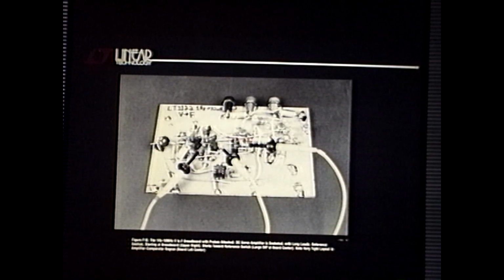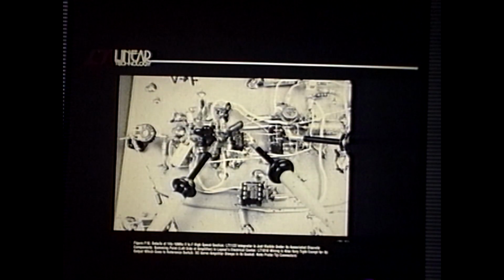But things get tight again in the switched voltage reference section up in here, because this does have to move at some speed. You also notice the probes, there's no ground straps. I've got tip adapters here. You can really see it now in this picture.